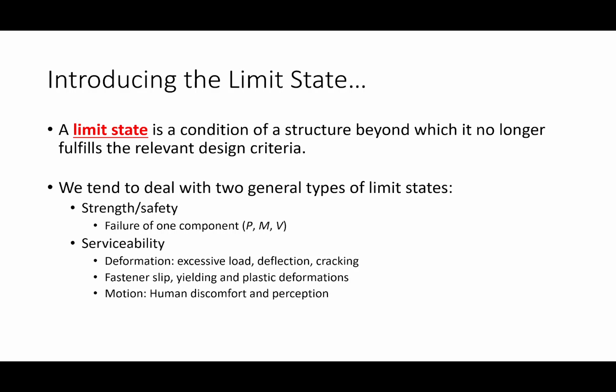So, for example, a tension member is me taking a piece of steel and yanking on it. There's a couple of ways that that member could be deemed to fail. One of them is going to be called yielding in the gross section. One of them is going to be called fracture in the net section. What if the member is fine and it's the connection that fails? Maybe the bolts fail or the weld fails. Maybe there are some other connection-related phenomena that we need to consider, and what have you. And we could go on and on.